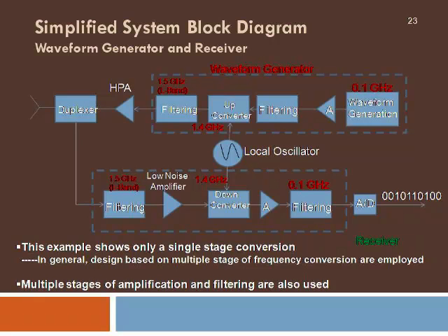Then any unwanted thing will be filtered out by this. Now we have the information of the target available on the 100 MHz signal. So to process it efficiently, we go for A to D conversion and put these bits into a processor for removing the noise, distortion, etc., and to decipher the target coordinates accurately.